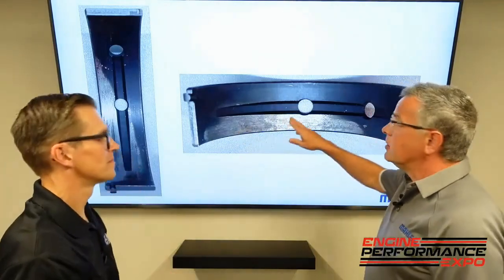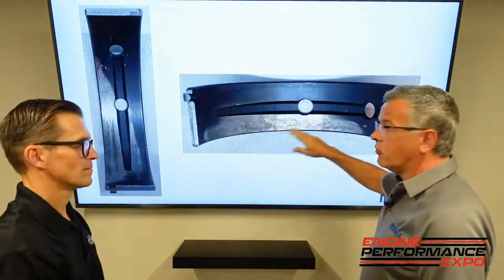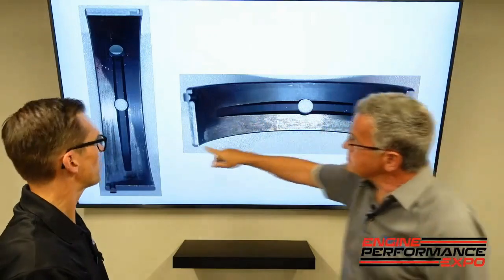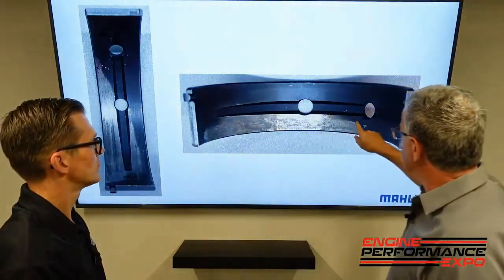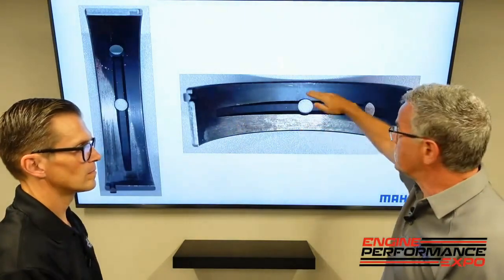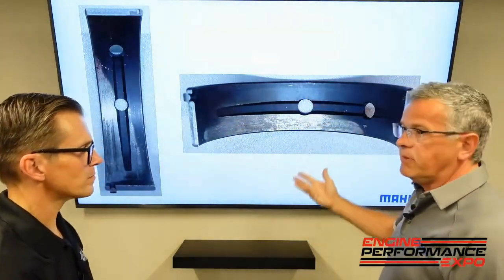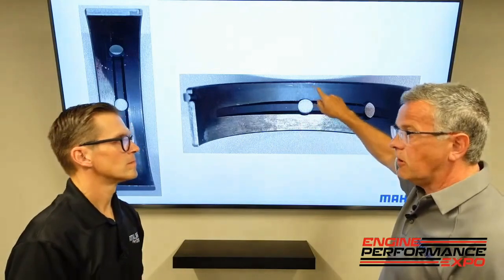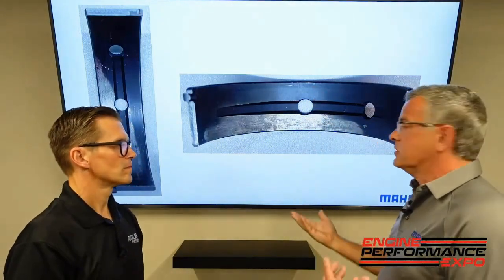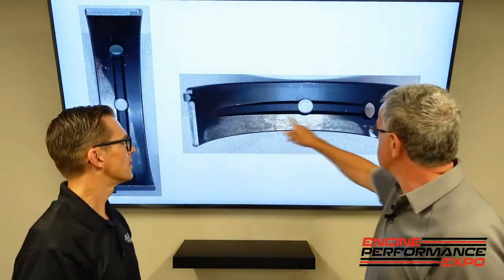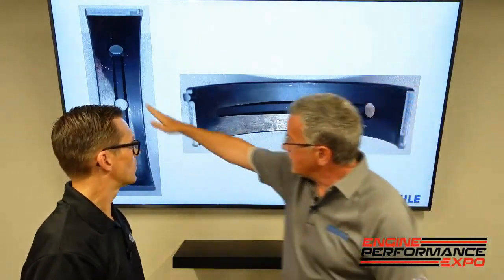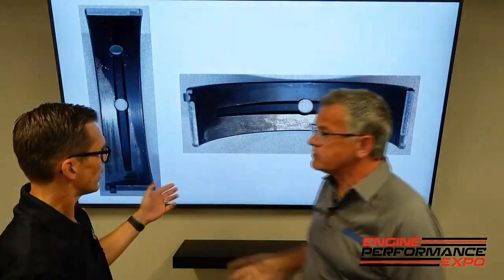Yes. Same bearing, same engine, number 4. Same thing. You can see there's different deflection going on in the crankshaft, but you can see how it's wearing on half of it, but not the other half. So a lot of people say, "Well, it can't be because my bearing looks good on this side." Right. Well, you're taking the fact that the crank is staying straight, and we know that's not the case. Right. This is showing because of where it's at, and again, this one's actually at an angle where it's loading.